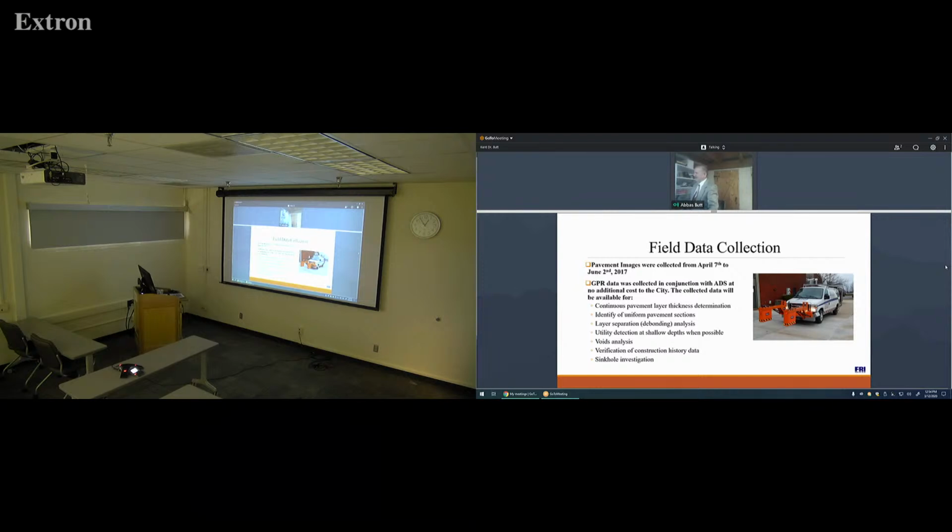In our case, we are not collecting the GPR data along the full width of the pavement. It is a line track option, where we collect GPR data just in the wheel path. Therefore, if the void happens to be under the pavement in the wheel path, and at a shallow depth, then we may be able to pick it up.